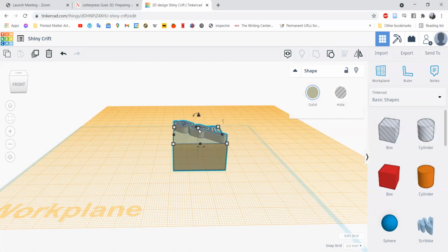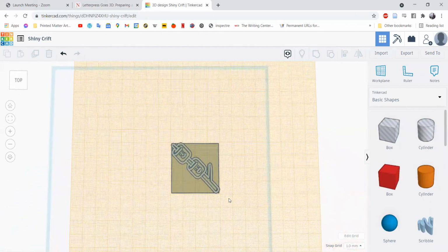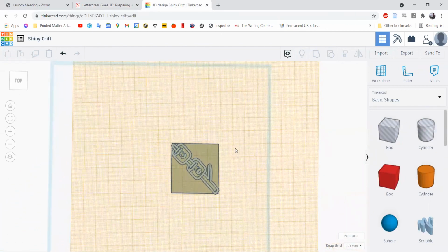You're then going to want to select the height box. Letterpress height, or type high, is 0.918 inches. We want to be just a little below that. It's better to be a little below than a little above, and sometimes 3D printing can be somewhat imprecise. So we are going to go with 23.1 millimeters. Note that the entire design shifted down slightly. And with that done, we're ready to go.